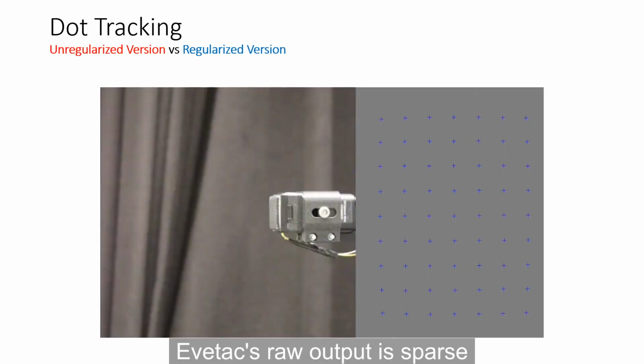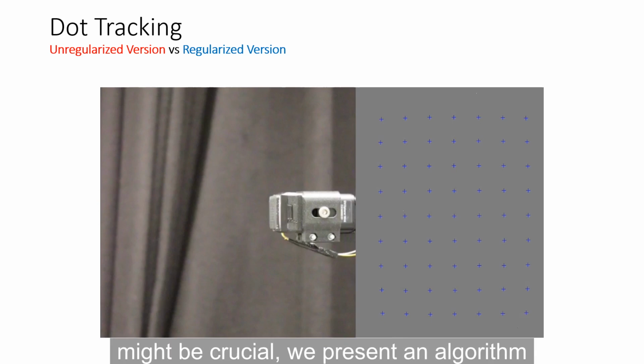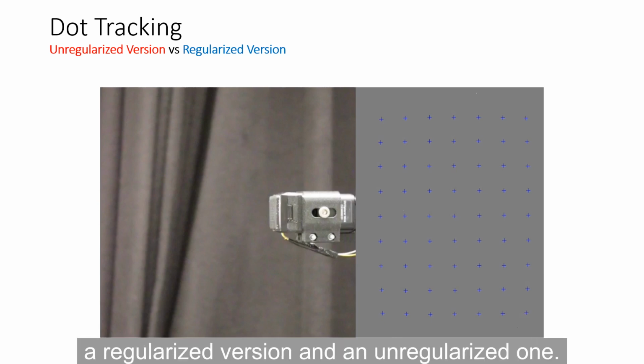Evetac's raw output is sparse and solely contains local information. It is thus not possible to reconstruct the current global deformation of the gel given single measurements. However, since this information might be crucial, we present an algorithm for tracking the dots imprinted in the gel. We investigate two versions of the algorithm, a regularized version and an unregularized one.